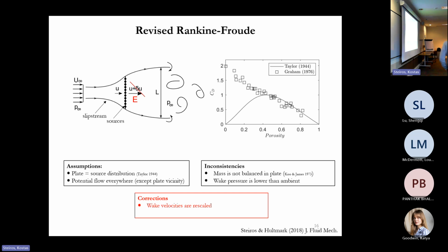And then in 2018, what I proposed was another deficiency of this theory. The idea is that when we go to lower and lower velocities, we expect the pressure here in the wake of the body to be lower than the ambient, than the atmosphere, for example, P infinity or P atmospheric. Whereas potential flow theory says, no, it has to be atmospheric.